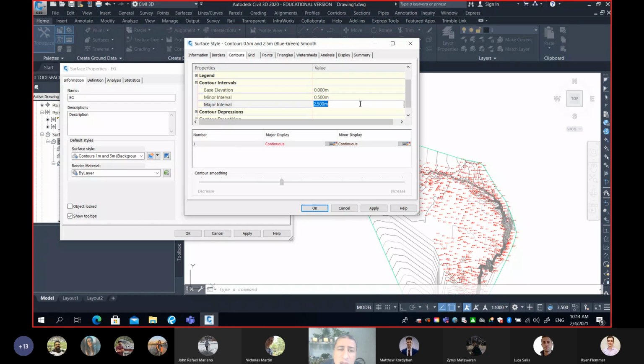Great. Now I'm going to minimize my interval. Remember, the last feature of my style is to make a smooth contour, very smooth. Do you see anywhere on this window that there is a potential that we can change the smoothness of my contour lines? Any help? Contour smoothing. You can see, thank you so much.